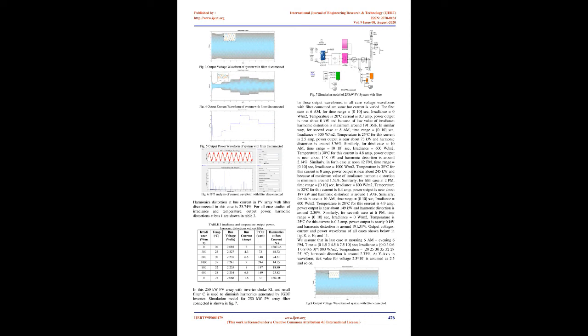Total harmonic distortion is the measurement of the harmonic distortion present in the waveform. Normally, two types of harmonic filters are used in the power system to mitigate harmonic distortion, i.e. the active harmonic filter, AHF, and the passive harmonic filter, PHF. To achieve acceptable distortion, reduce harmonics, and improve power quality, a shunt harmonic filter connected in parallel is used to mitigate harmonics, and practical passive filters are installed because of their easy availability.